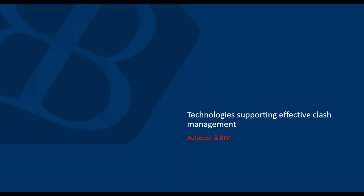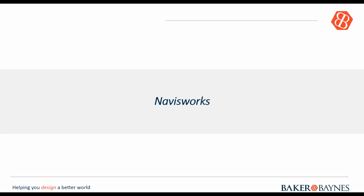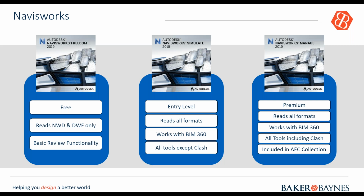Okay, so let's look at the Autodesk solutions for clash management or coordination management. The first one would be Navisworks. Navisworks is desktop software, and there are three right now. The first is Navisworks Freedom, which is what the name suggests: it's free. It's free to use as a viewer. It reads NWD and DWF only.